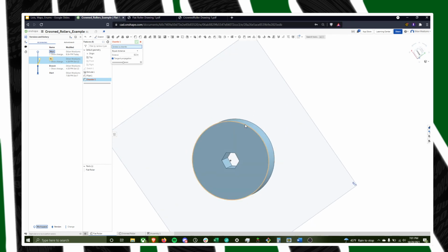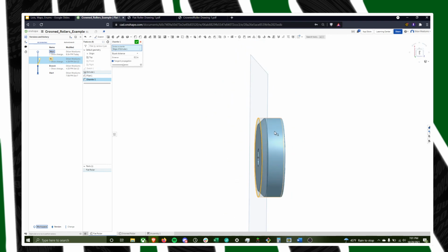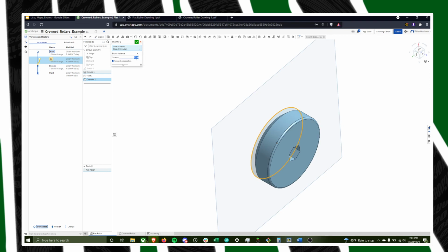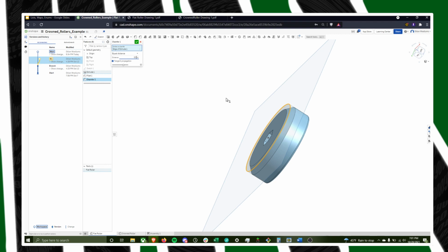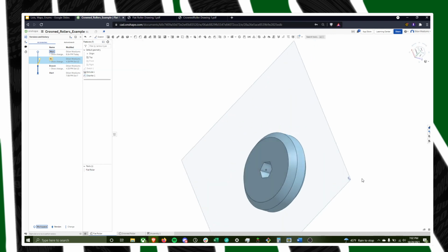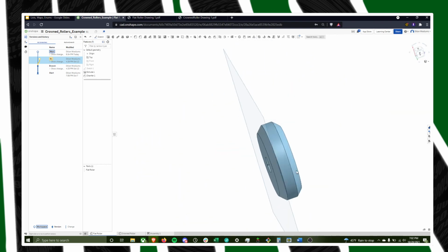Then a chamfer is a kind of beveled corner, kind of squared off. We actually could have made our rounded rollers by picking the OD and then doing a fillet or a chamfer and picking the radius. It's just not how I wanted to do that. And the distance works a lot like the radius, except it's straight across, 0.5, just like that. And if we wanted to, I could do a chamfer on two surfaces, and bam, this flat roller is now a crowned roller. Not at the right dimensions for our robot, but that is technically a crowned roller.